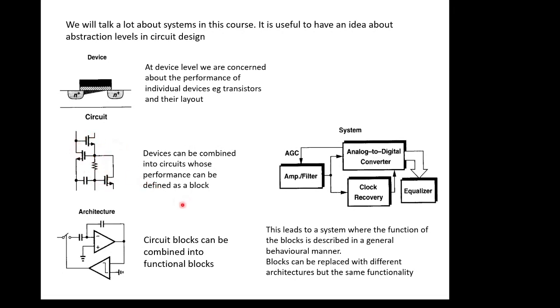And these blocks then turn themselves into architecture. And obviously something like an op-amp is an architecture because it's made up of loads of different transistors. And we're not interested in what's in the block. We're just interested in the overall performance of the block. And that can lead us to an architecture here, which is some kind of switching integrator circuit. And what's actually in these triangles we're not that interested in. We just want to know that they perform the same as each other.